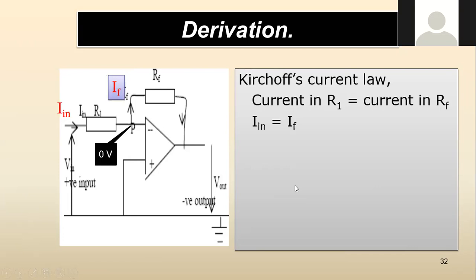That's a 0 point, the point P, 0. So it's always starting from the positive terminal: minus 0, divided by R1. Is that current I in? And then remember this is negative and this is positive. So it's 0 minus that, divided by RF.